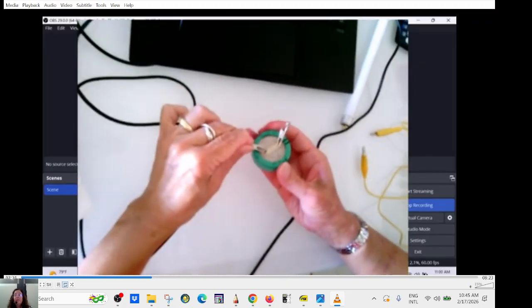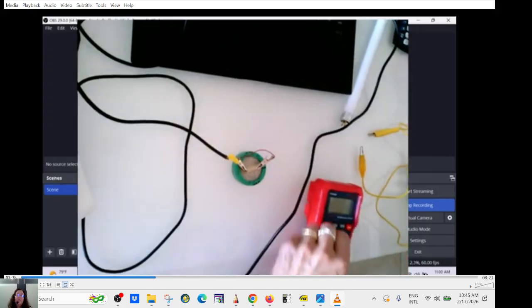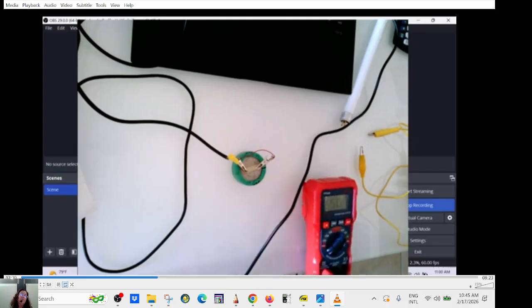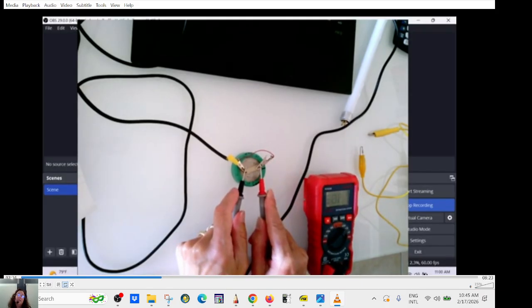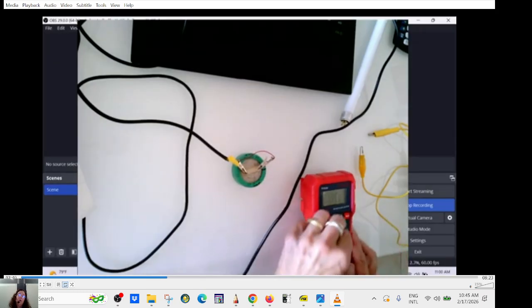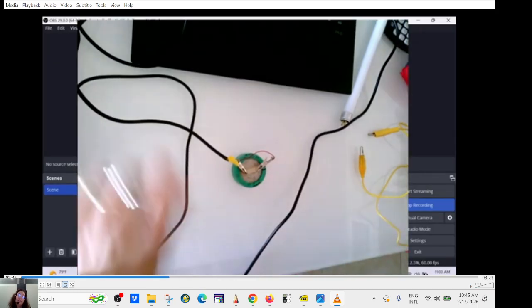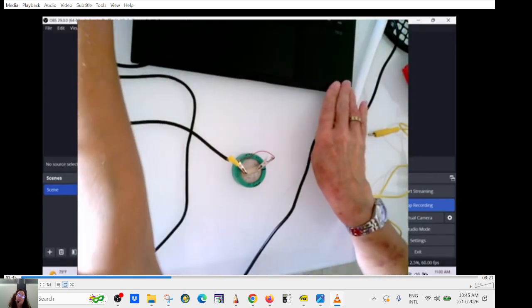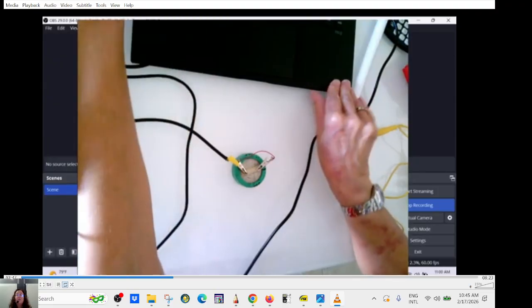And it's polarized, I have to be careful. You can find that it's going to increase to 5 volts. So you are charging your capacitor. It doesn't take long because I didn't put any resistance. So it's going to hold the charge. I'm going to disconnect, not touching it. If you touch, that's it. It's going to discharge.